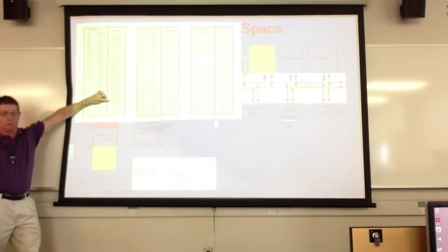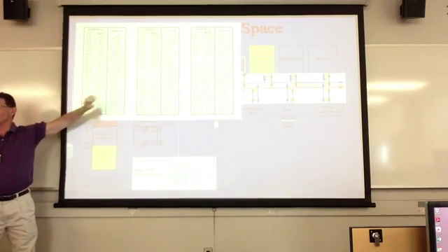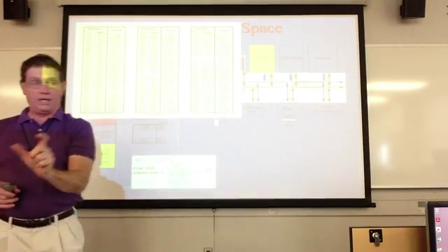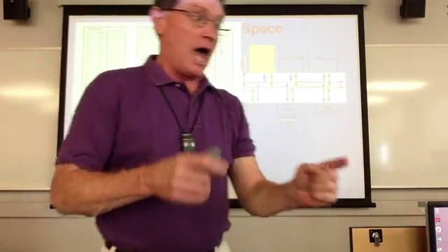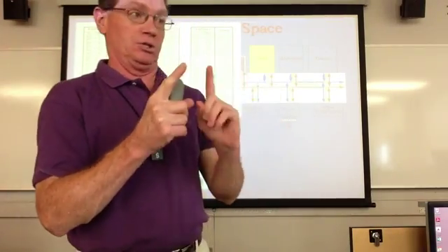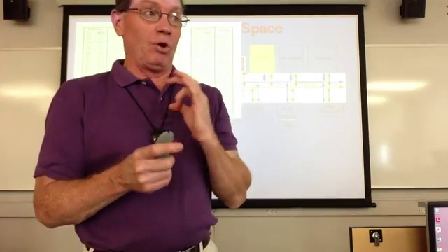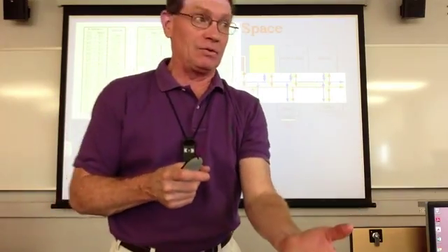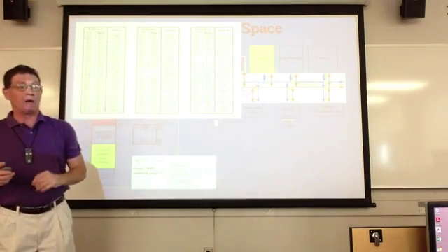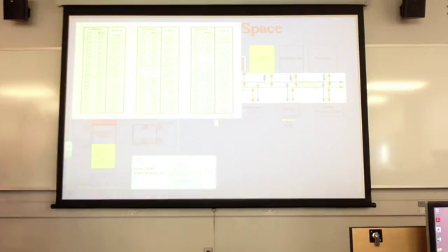You have two ports on your Butterfly board: port B and port D to play with. You can take any one of those 8 pins on port B or any of those pins on port D and selectively make them inputs or outputs, so they can accept a voltage in or put a voltage out. In these slides, I'll be showing you how to write to the LEDs. The other day when you got your little boards, you were basically writing to the speaker, physically writing to the speaker. We'll get to that code in a little bit.